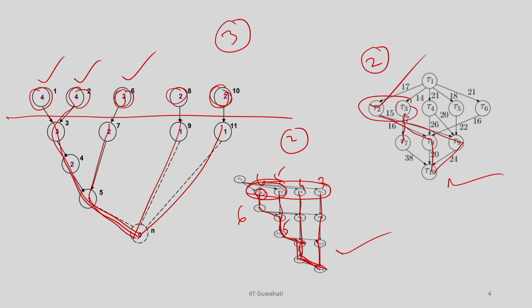So this is the heuristic that I just talked to you about. The first heuristic that we talked about is that among the nodes, you select the node which has the highest level or priority. That holds perfectly here, but as I mentioned, since all the nodes have a distance from the sink node of 2, that particular logic will take an arbitrary one, and that arbitrary choice may not give you the best solution.